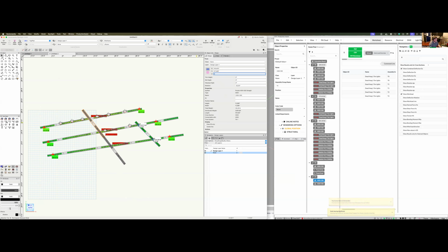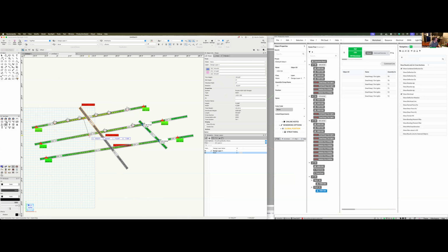Sometimes, rather than stacking trusses directly, you need a drop between them. Production Assist offers a dedicated Insert Drop mode for this purpose. Activate Drop mode by choosing the Insert Connection command and selecting Insert Drop mode. Start by selecting the truss that will serve as the lower element.